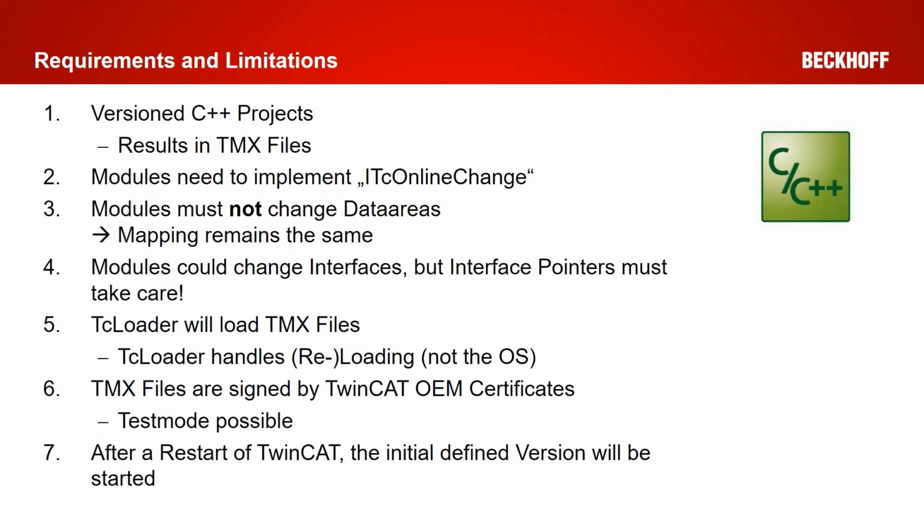Because if you have an interface pointer and this is exchanged, you need to deal with the fact that it is exchanged because maybe it's not available anymore after the online change. So take care about interface pointers if you're using them together with the online change. The TwinCAT loader is then the component of TwinCAT which is actually loading the TwinCAT Module Executable files.